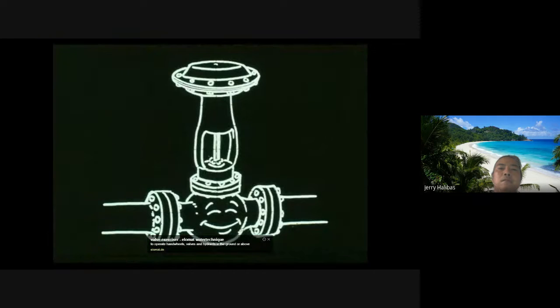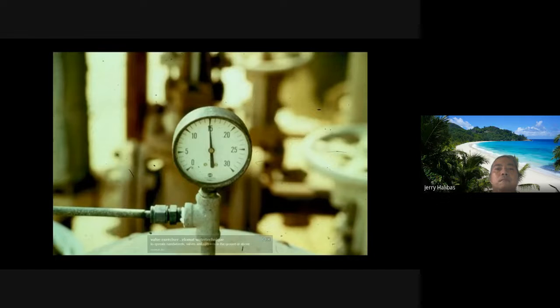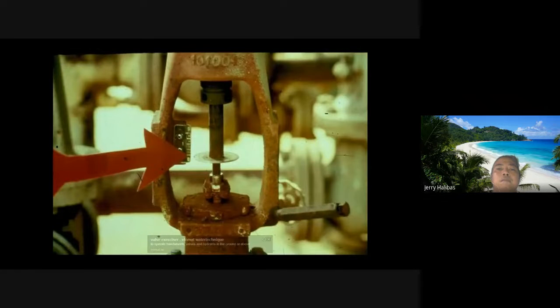Suppose an operator tells you that a control valve is sticking, stuck, or controlling poorly. This problem is not obvious. You will have to troubleshoot the system. First, ascertain that the instrument signal is reaching the control valve. This controller has 100% output. You would expect the signal at the control valve to be 15 psi. And you would further expect the valve travel indicator to show 100% valve travel.